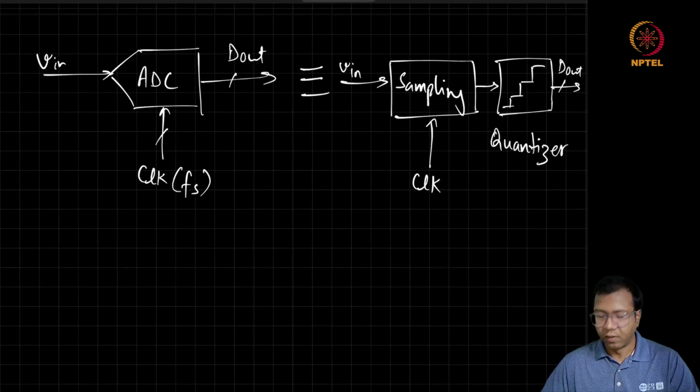Okay, so when we are talking about digitizing the signal with the help of an ADC, we also need to ensure that there is no loss of information. At least for our discussion about channel selection, we will assume that there is no loss of information because of quantization, just assuming that we have sufficient resolution in the ADC. So we will focus mainly on the sampling aspect, and we need to make sure that as a result of this sampling operation, there is no loss of information.